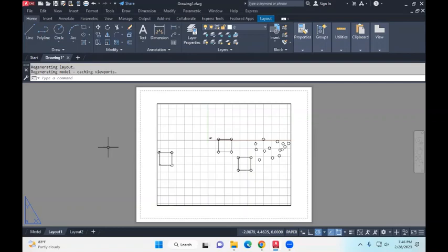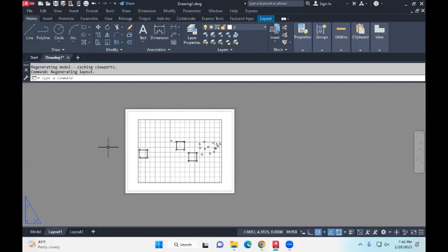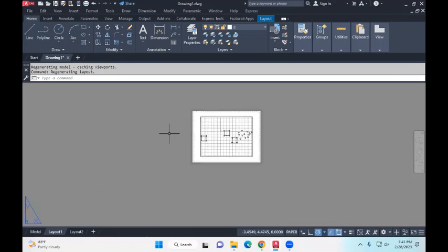Okay, so the first thing to do is, once you go to the layout, I would like all of you to pay attention. Okay, you can look at the screens. After I give you an example, I'll redo it. Then you follow. So we have to set up the page. Right now, if you zoom in and out, are you zooming in and out of the drawing or zooming in and out of the page? The page, right? You'll see that white screen, that white thing is the page. Everything outside, which is the gray area, is not the page. So you're zooming in and out of the page.